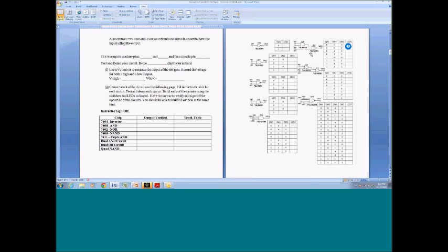I try to drive home the idea that you really want to have a power bus on the top and a ground bus on the bottom, and pull all power and ground from that. That's explained in Ray's video, actually. Not Ray, but his document, which is really well done. But this is the only one I want to show.